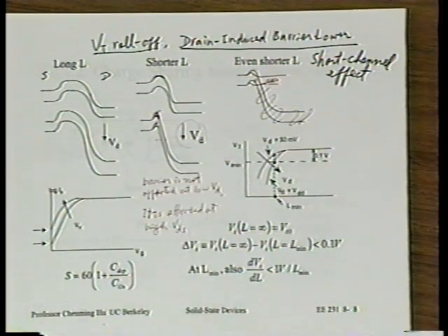Continue your question. So overcoming or reducing short channel effect means that there is no drain-induced barrier lowering. So there has to be some region where the potential difference, the barrier, is at the maximum value. Is that what you try to achieve? Yes, it is. That's correct. All right. Okay, great.